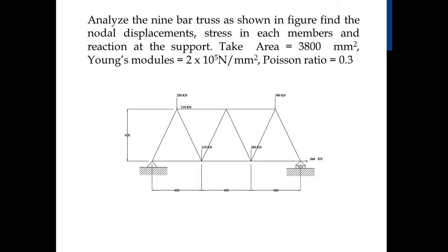One-dimensional truss element problem. It consists of a nine-bar truss as shown in the figure. We are going to analyze this truss by using ANSYS software. From that, we can find the nodal displacement, stress in each member, and the reaction at the supports. The truss material is considered to be steel.